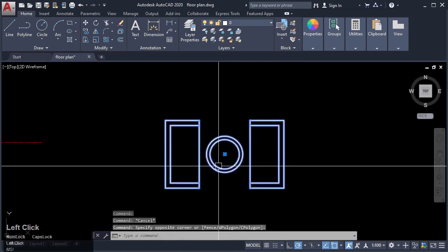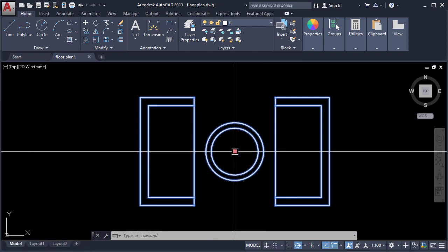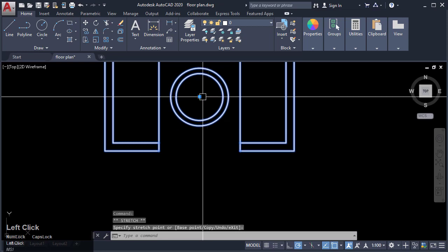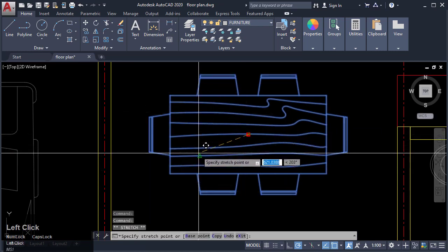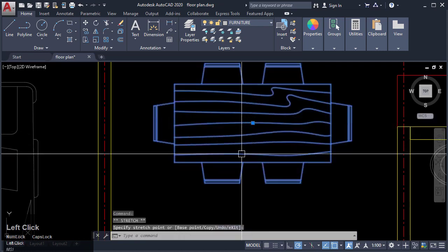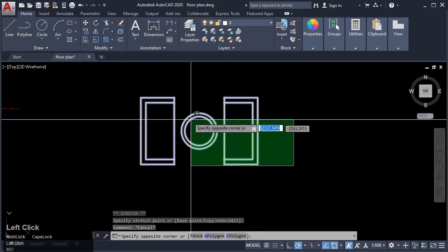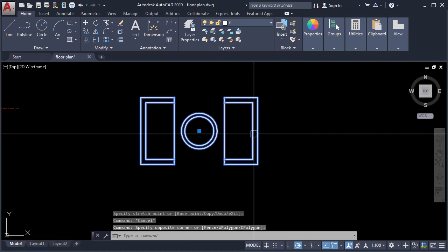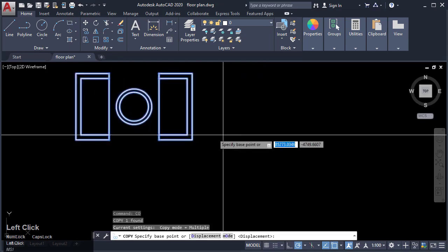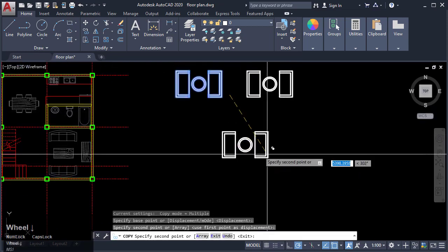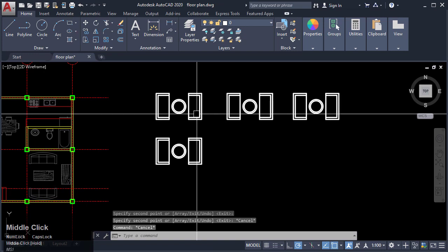Now in a block, what happens is that the entire entity is selectable only on a single grip point. You can now use that grip point to move the object, similar to your other blocks. Now to edit your block, you can actually edit that one under your edit block command. But to reflect the effect of a block on other entities, let's create now copies of that block so that you can see the effect of editing one block to other copies of it.